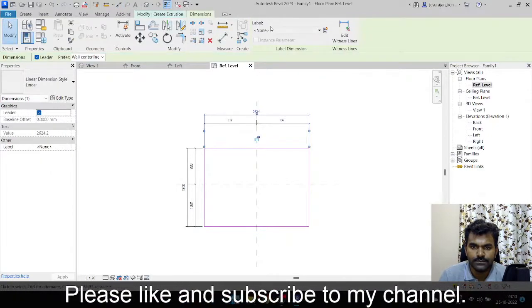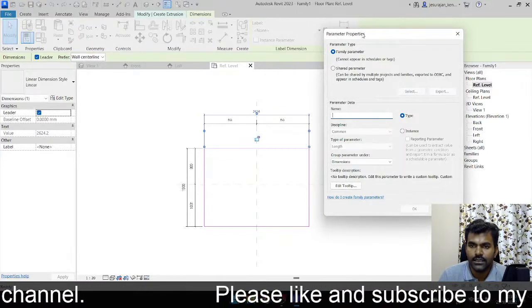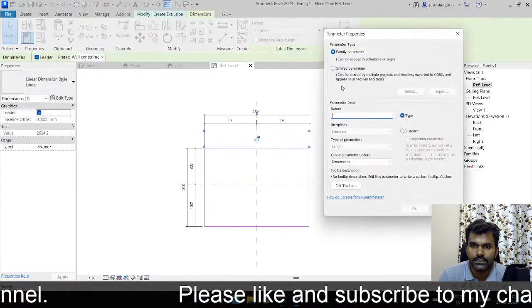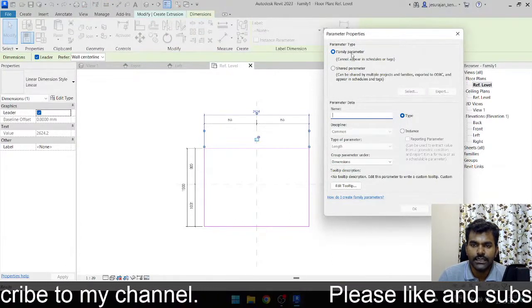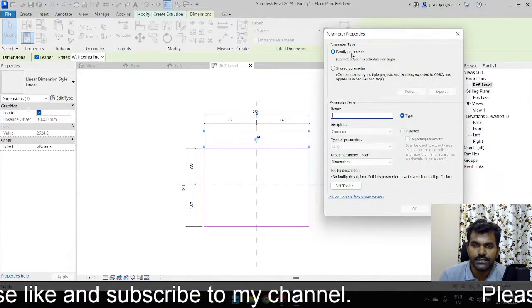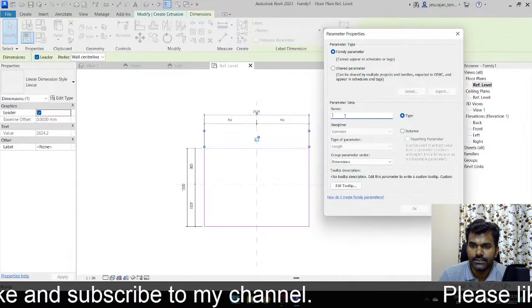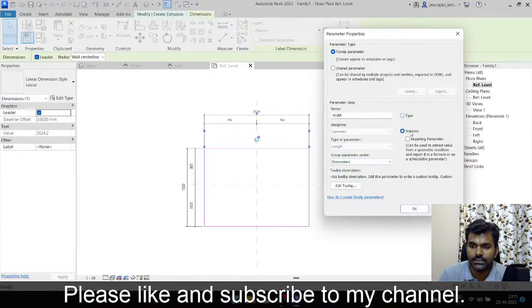Select the dimension and create a new parameter. It's a family parameter for now. In case you want to keep these values in a table, then you should create a shared parameter. Just to do it quickly, I'm selecting family parameter and just give width, and keep this as instance.